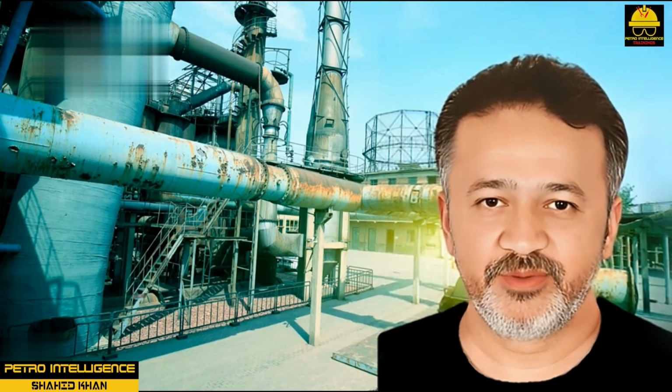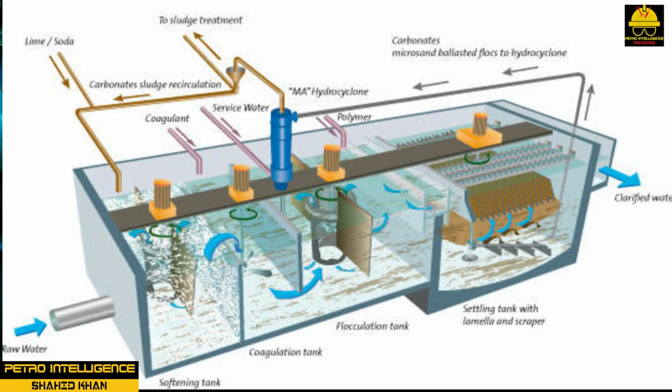Modern manufacturers use two approaches when adding lime soda for water softening: batch and continuous. Batch uses only one tank. Continuous softening uses multiple compartmented tanks, continuous additive addition equipment, and retention time for chemical reaction, sludge removal device, and clear water draw-off.